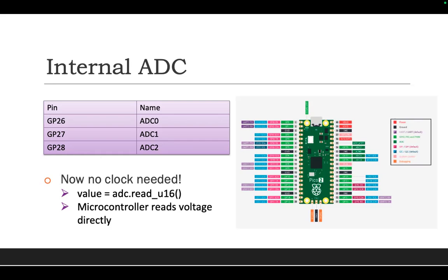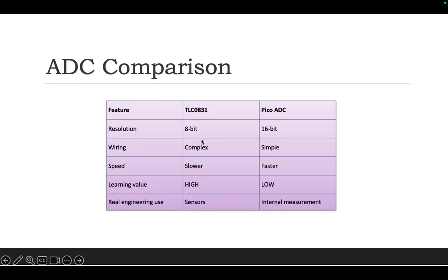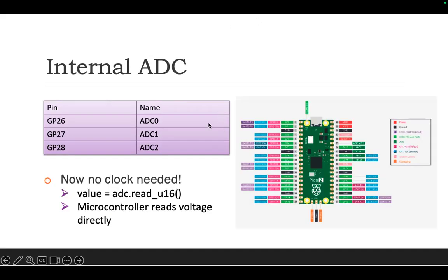The function is the same, but remember those 3 cannot work at the same time. Only one pin works at a time, so you need to pay attention to that. In future labs and the final project, if you want to use multiple pins, finish using one and then use the next. Just remember that.